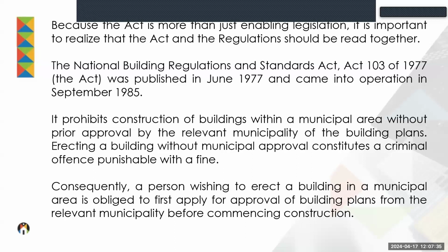But the Act said that all buildings have to comply with the National Building Regulations. The only issue at stake here is the submission to the local authority for approval. So if you've got a building on farmland, it doesn't matter when it was built, it had to comply as of 85 with the National Building Regulations. The only aspect was that it was not required to be submitted to a local authority because it fell outside the area of jurisdiction of the local authority. But for health and safety's sake, those buildings still had to comply with the requirements of the regulations.